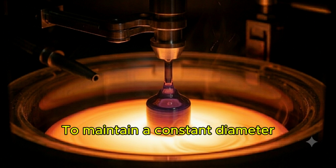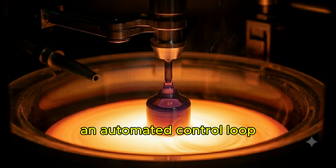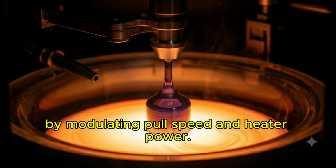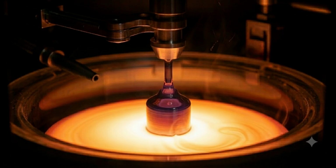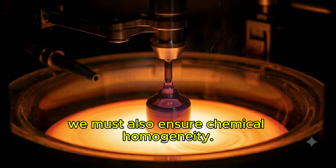To maintain a constant diameter throughout this long cylinder, an automated control loop constantly balances the thermal environment by modulating pull speed and heater power. But maintaining a constant diameter is only half the battle. We must also ensure chemical homogeneity.